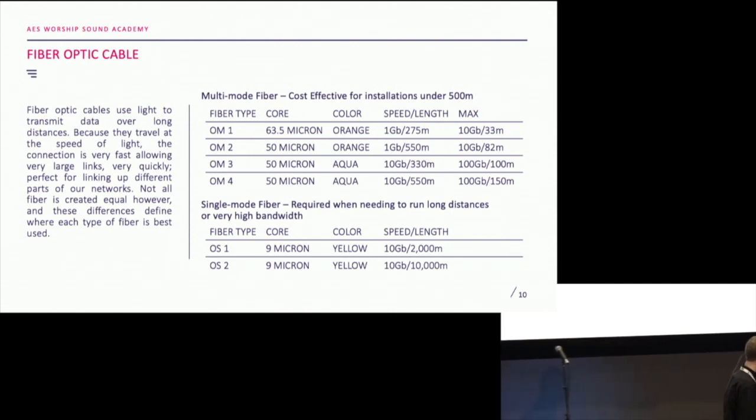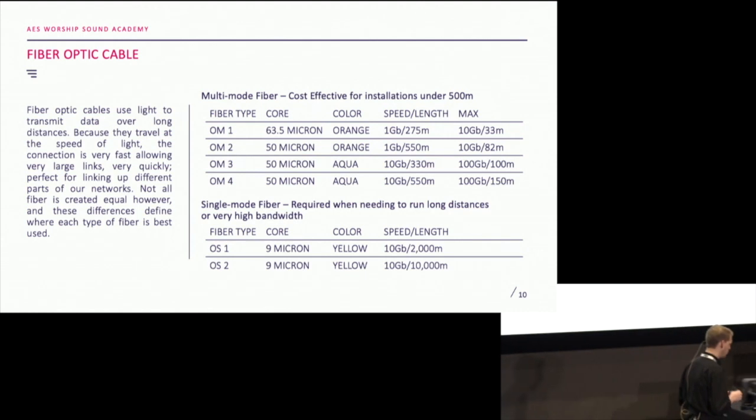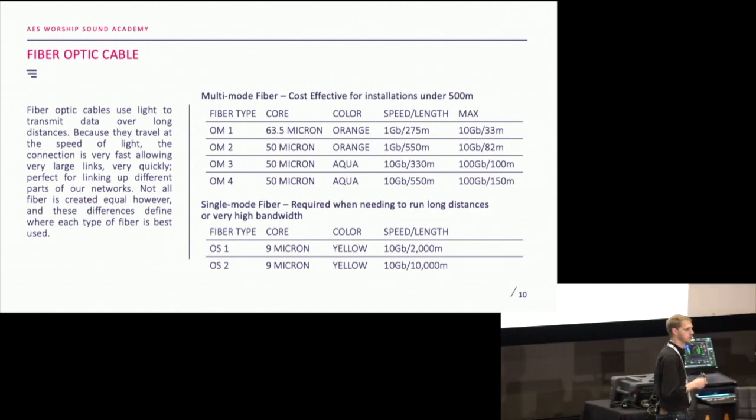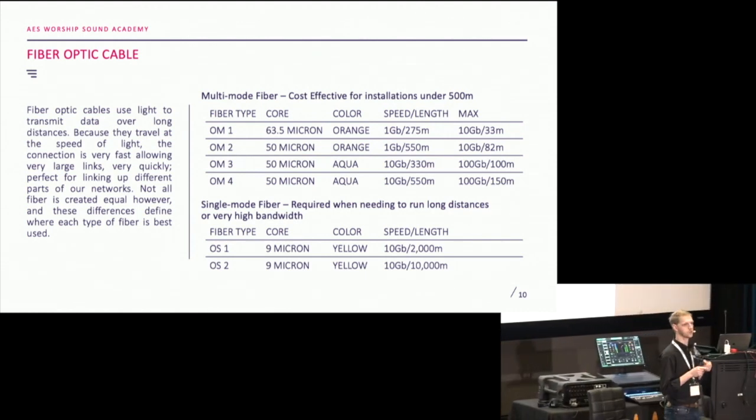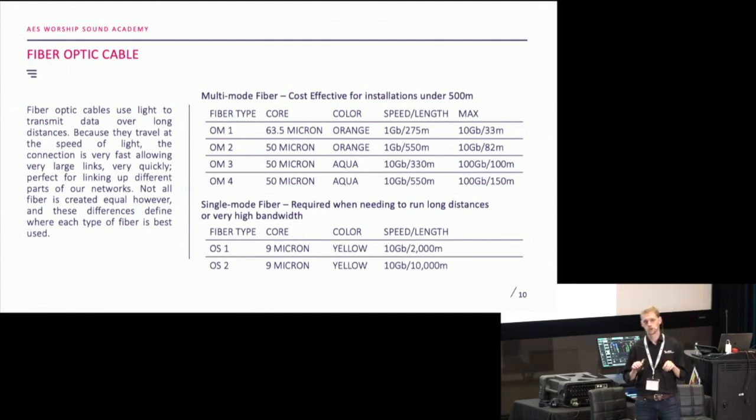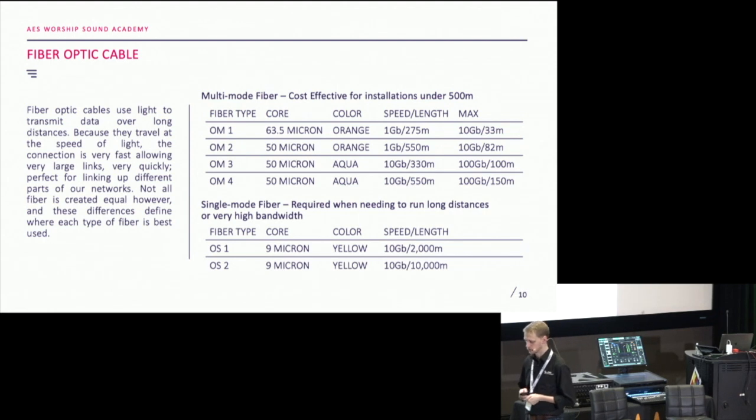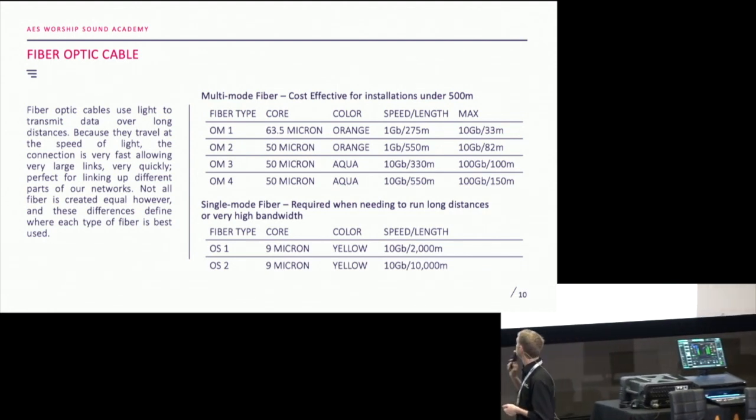gig link, right? So most of the manufacturers that are doing fiber consoles, that are doing fiber switches, are going to say, let's go ahead and provide and install OM3. All the Neutrik opticalCON, if you get the multi-mode version, it's OM3. If you get the single mode version, then it's going to be one of the other single mode options. So be aware of that.